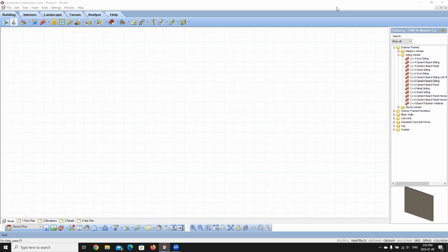So let's get started. First thing we're going to be looking at is specifying quantity information for elements. Before starting a model, it is good practice to open your catalog and specify the quantity information for elements that you intend to use in your design. You can change the information such as the price, the supplier, the part numbers, and any units for pricing. The more fields that you fill out on an element's quantity properties page, the more information you will see reported in your estimates and quotes.